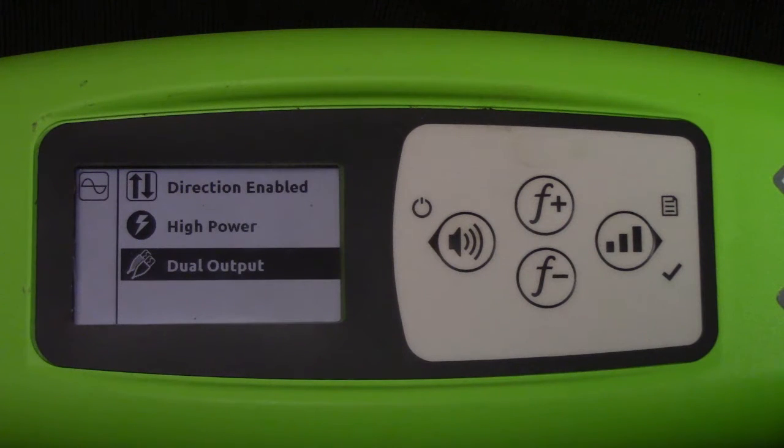And then you have your dual output feature. With your dual output feature, you have your leads with the 3 wires, the black, the white, and the red, the black being your ground. And then you've got the white and the red output leads. You have the ability to select between those leads as to which one you want the signal going out on. That gives you the ability to hook to 2 different utilities, trace one out, and then remotely change the transmitter and trace the other back. This feature is only found on the advanced unit.